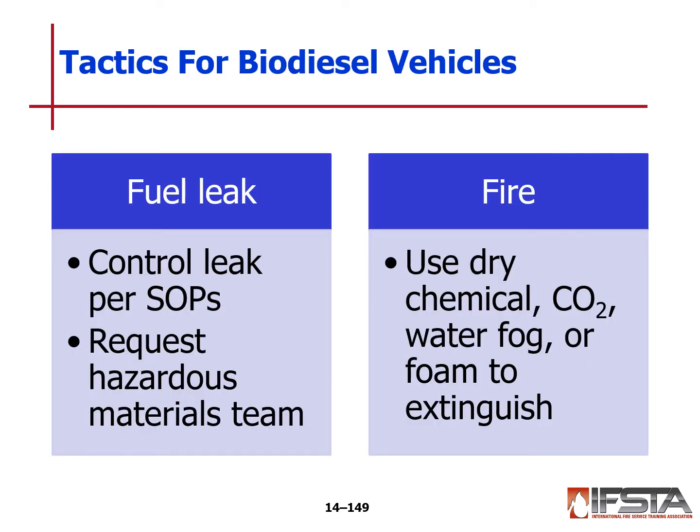With a fuel leak, we want to control leaks per SOP, like we would control a diesel fuel. We may also, depending on the amount of product that we're talking about, request hazardous material teams as well. With a fire, use dry chem, CO2, water fogs, or foams to extinguish.